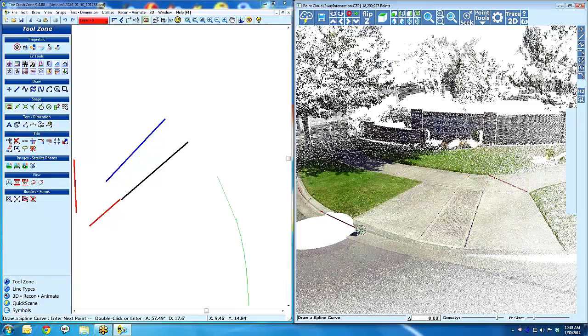And as I'm going along, if you look down here, this is our delta Z area. That shows us the change in height from the last point we clicked on. And why is that valuable? Well, right now it's telling me 0.01 feet or 0.02 feet. It's really going to be based on what our units are set to, so I'm set to feet.